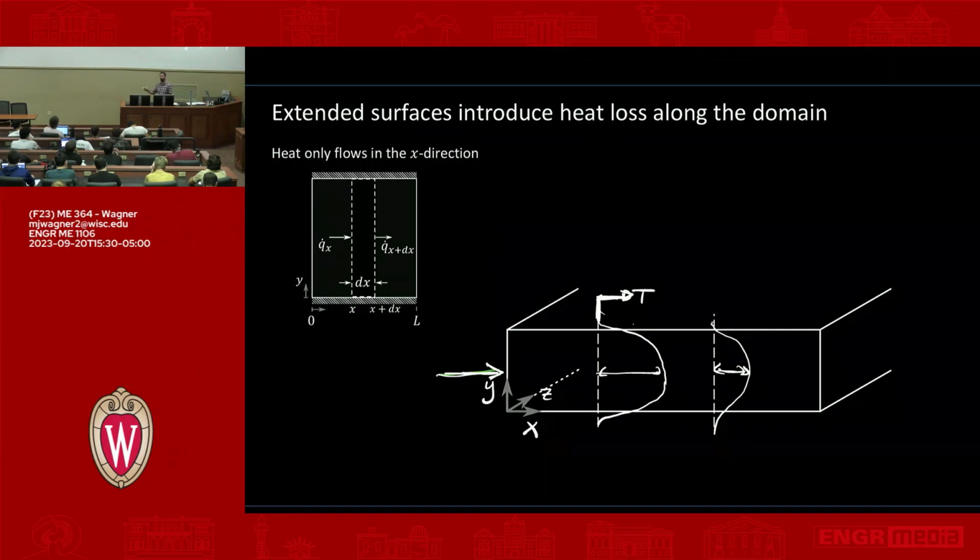What are the requirements for a 1D model? Well, I basically have to prove that there's no significant temperature gradient in the y dimension. So what I'm saying is, if we had a temperature gradient that was basically this, and then basically this, right? That's a 1D model. There's no y dependence of temperature. So I can get away with just a 1D simple expression for that. Okay, so if we're all on the same page there, I'll tell you how we get to this point. All right, so let's go to the next slide here.